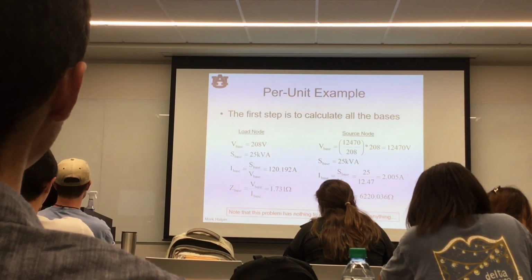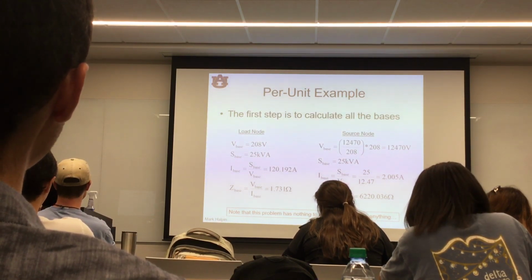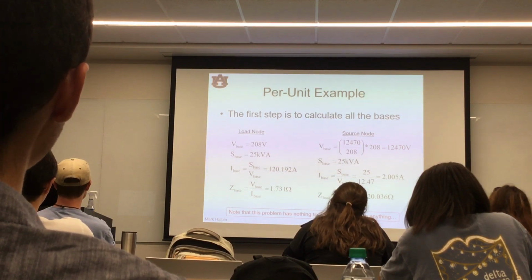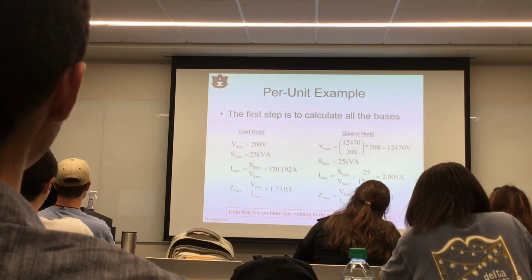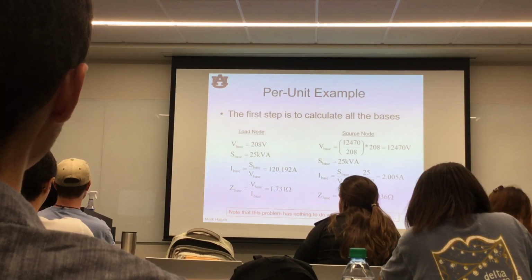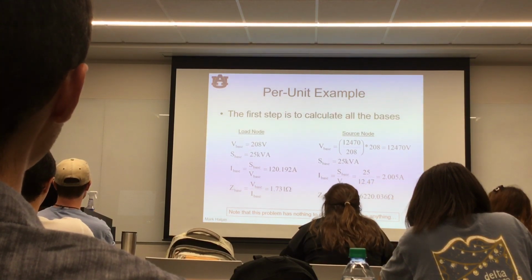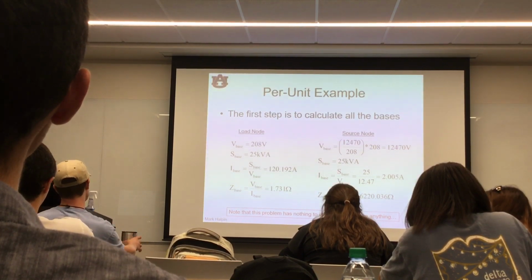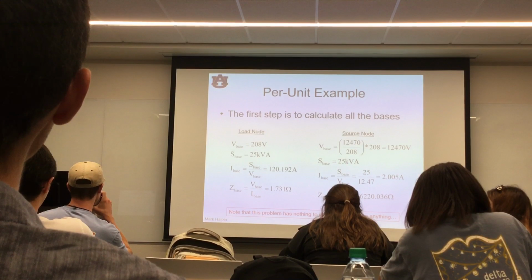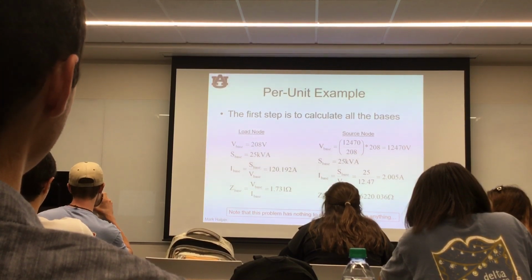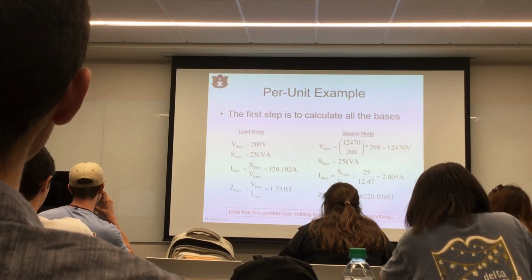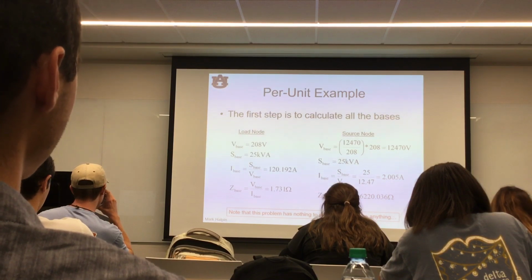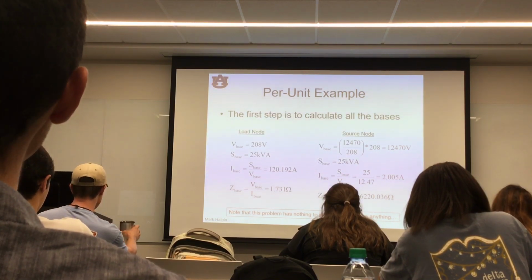That makes no sense. Bases, remember, all base is the base of what? We talk about a percent of what? Whatever the base is. I'd love it if Alabama Power sent me a bill and said, oh, my bill's 50% less. Great. My bill is 0 plus J something, the imaginary part. That makes no sense. Bases can never be complex. Never. That has no practical meaning whatsoever. So don't ever do that.